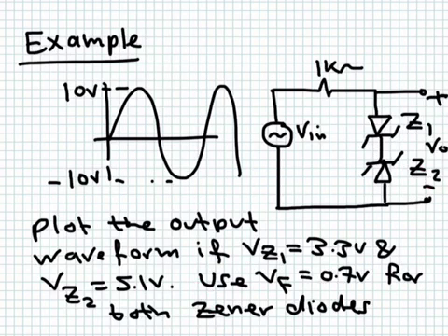A Zener diode is nothing but a diode. If I put a symbol like this one, this is simply a diode. It is exactly equivalent to a diode pointing this way. But in a Zener diode, the doping levels are selected such that it can reach breakdown earlier.